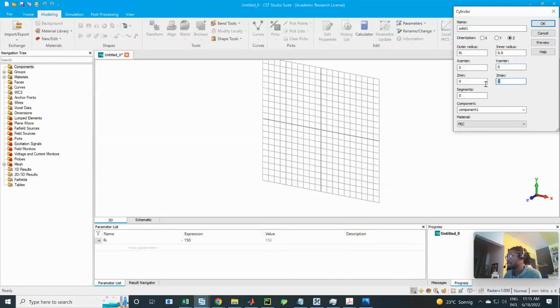So that's the first dimension I'm going to make up, and I'm going to call that the D tube. Okay, the length of the coupler. That's what I have to put in first. So I want it to be centered. So I could call it D tube because I want my tube to be right 2, then plus offset. Now don't bother too much about the dimensions. You could as well put anything.